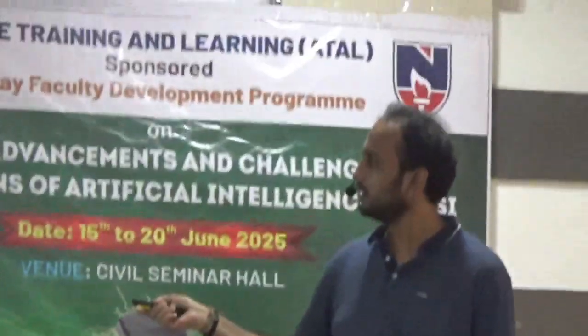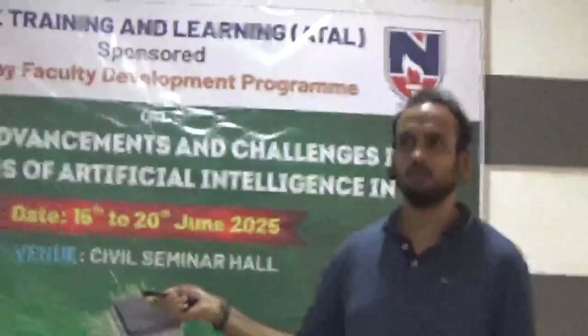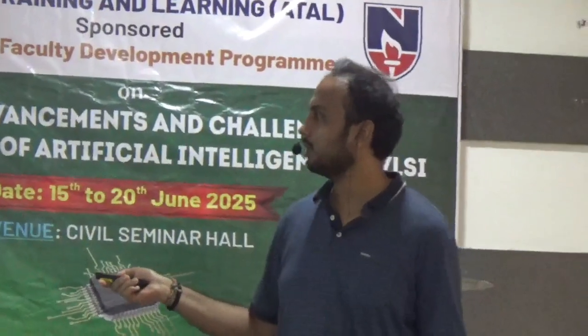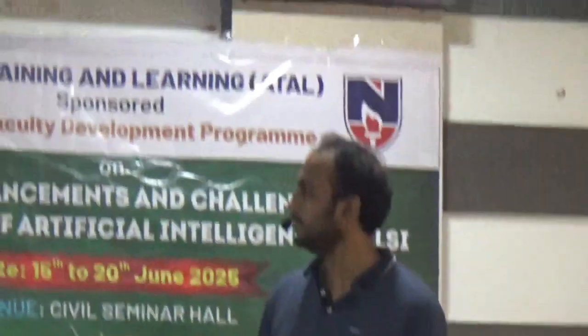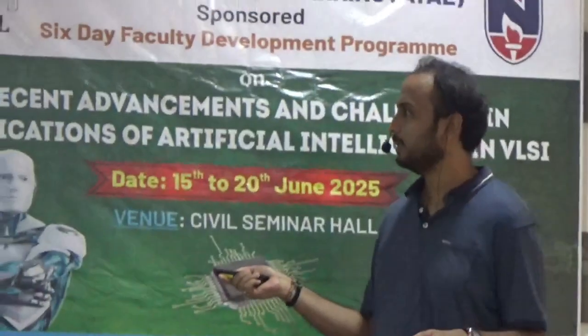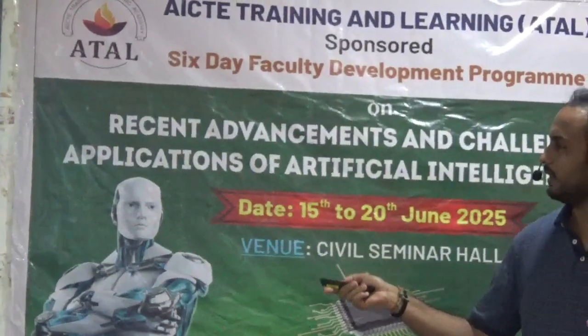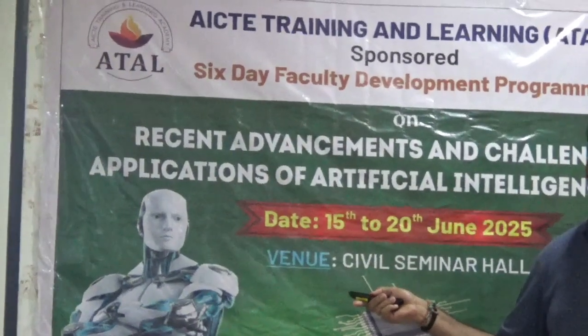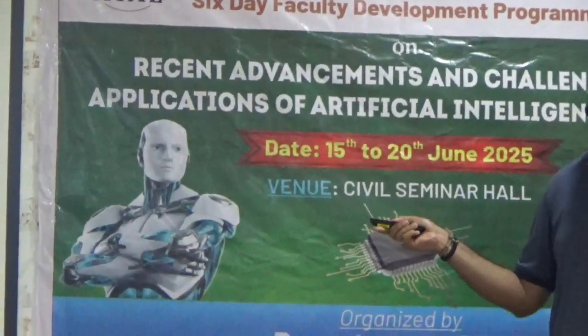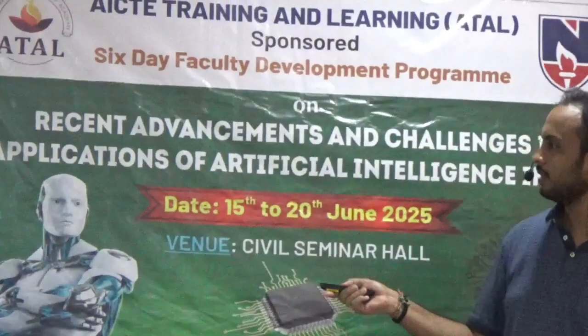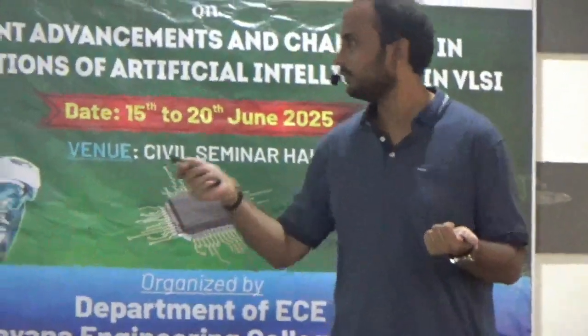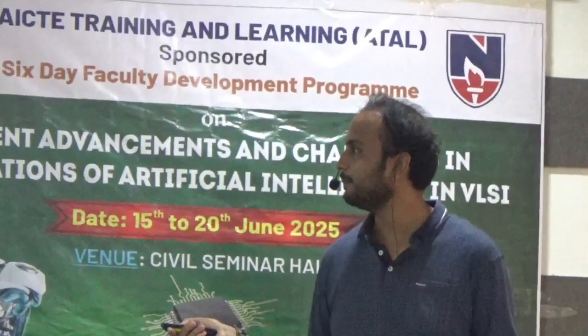When you go with velocity saturation, you will get the best gm, the highest gm. But the trade-off is that you will get a poor gm/ID. So when we go to the lower technologies, this is where we are. We always operate our device in velocity saturation. We will get a good gm out of the device, but very poor gm/ID. So we will see how this will impact.